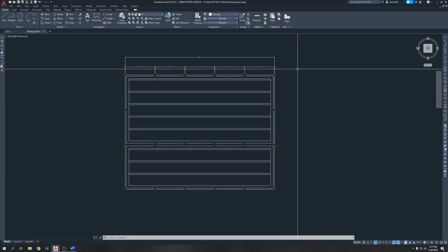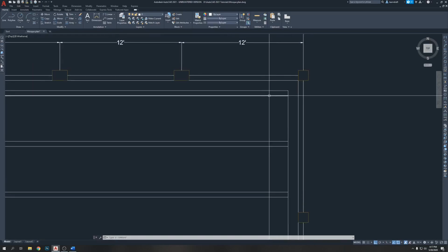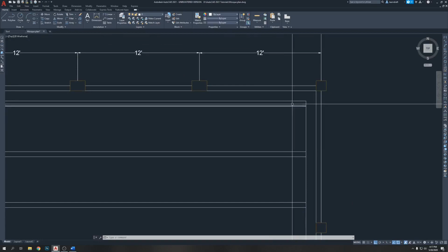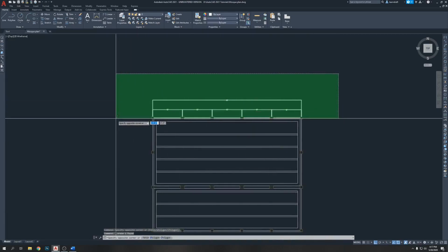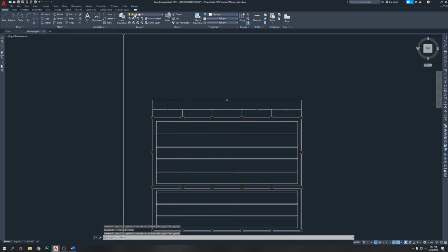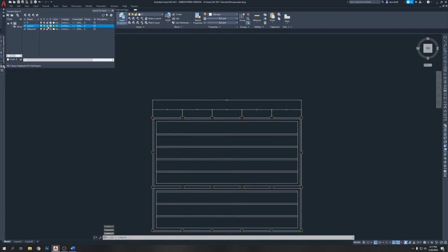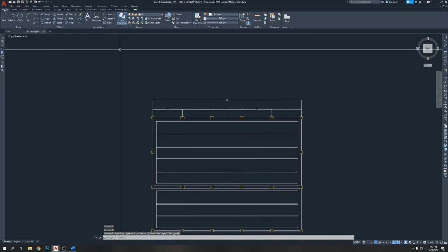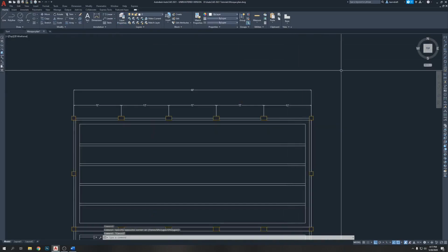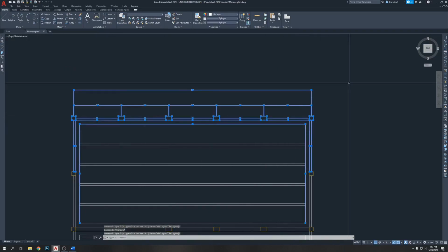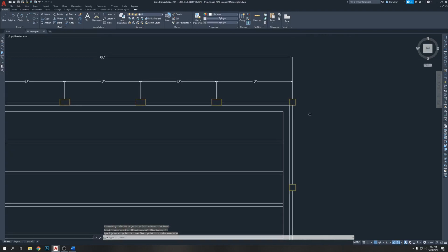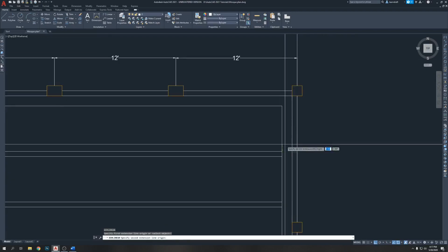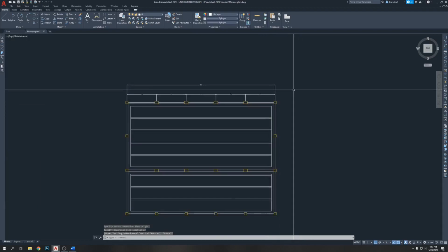Here is one thing, you see, this 6 inches we do not need, because this 6 inches was only for the separation. So what we're going to do is take out this line, delete, and unlock the column, otherwise it's going to stay there. Unlock the column, and we saved 6 inches. Okay, it's good. So DLI, enter, click, it's 4 feet 6 inches. This is good.